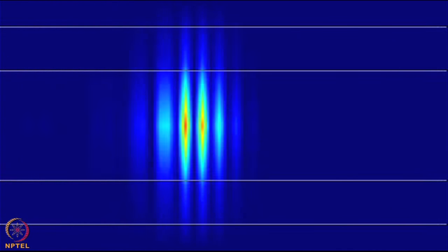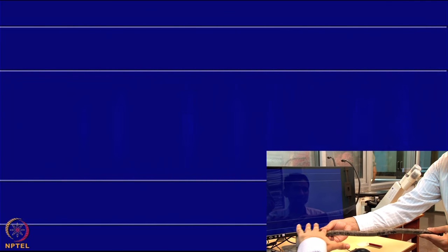and how we have done this using a finite difference tool. So this is lambda by 3, which is a straight waveguide. And you're trying to send a kind of a Gaussian pulse. I'm sending a Gaussian pulse and looking inside at the modes and how it's propagating.